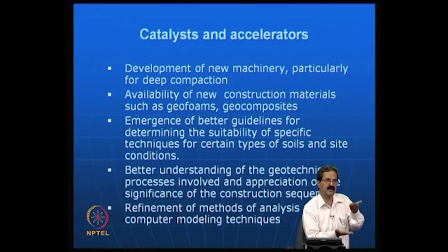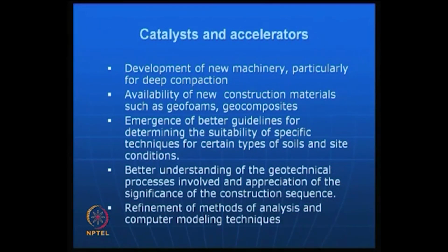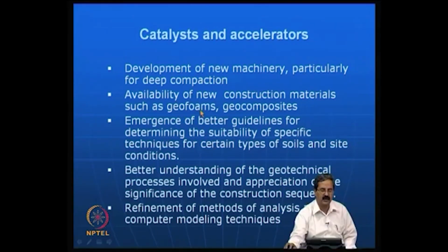That is why you have so many layers. Why? Because you would like to distribute the load to see that the subgrade is not affected to a maximum extent. But when you have a material, you just bring it in a truck and place it there, and then put some wearing course and merge everything, like a geofoam, which is not really compressible, it is fine for us. So, you can construct roads very fast. Geofoams are one. There are many actually, particularly in road construction, there are so many things that contractors should be ready to absorb as techniques.